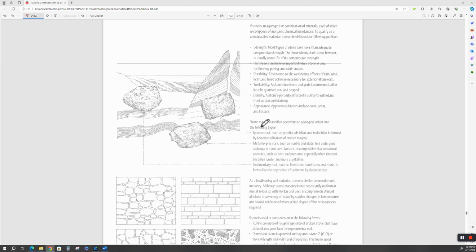I'm not opposed to stone. I helped my uncle build some structural stone walls, and we had plenty of limestone around his place, and they were a double wide wall. So you have stone on one side, stone on the other, randomly laid with a good adhesive mortar, and we'd fill this cavity in with mortar and reinforcing steel, and then you'd have ties going across here just like you would with regular masonry.